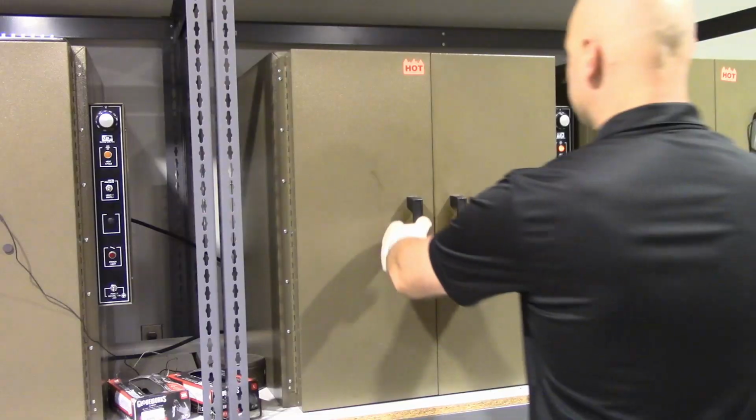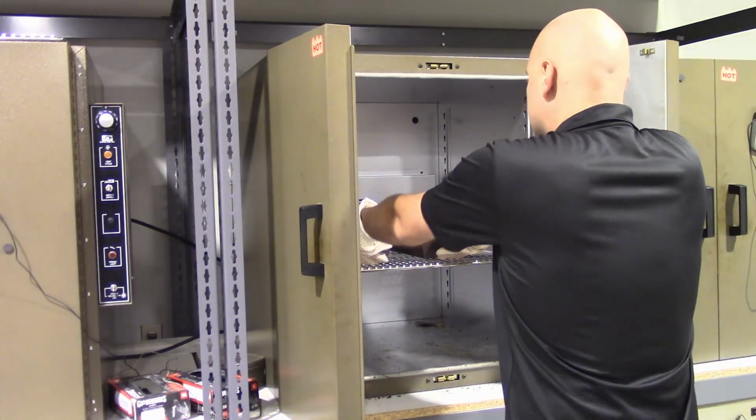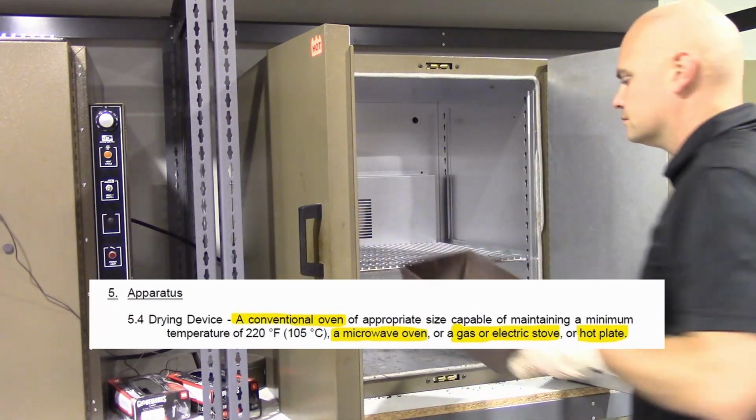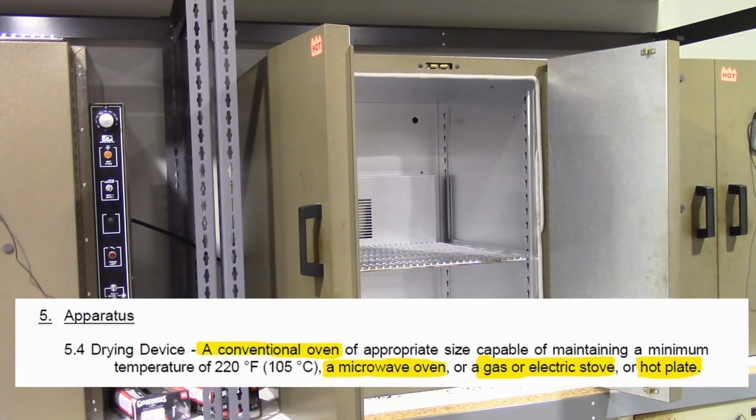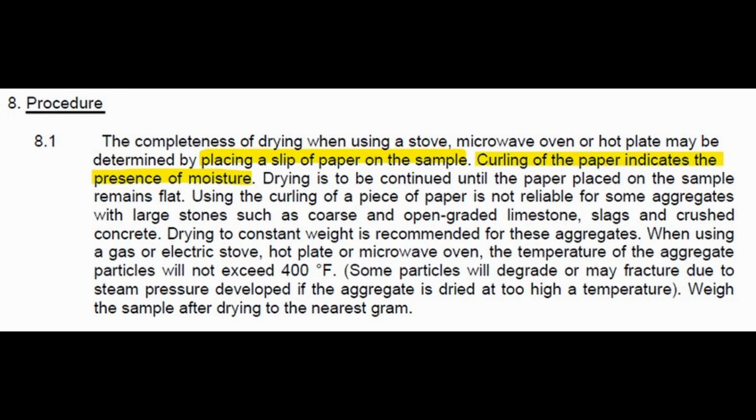MTM states that a conventional oven, microwave oven, a gas or electric stove, or a hot plate are available for this purpose. We must next verify that the sample is in fact completely dry. MTM allows for the use of the paper curl method to determine this. It should be noted this method is not reliable for some aggregates, including those with large stone, such as coarse and open-grade limestone, slags, and crushed concrete.